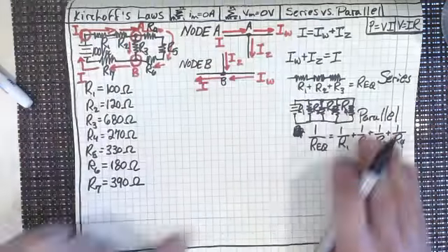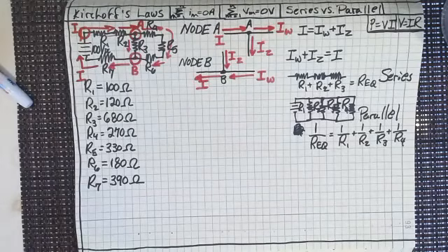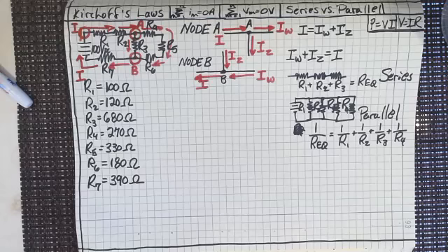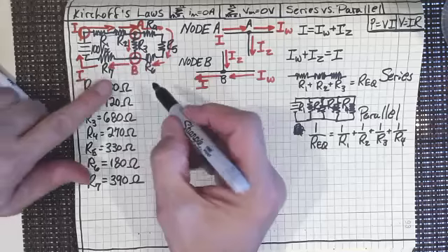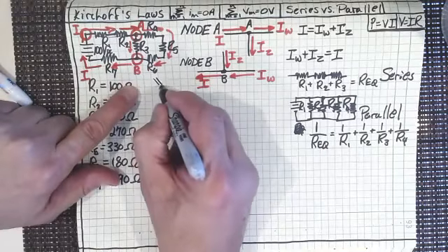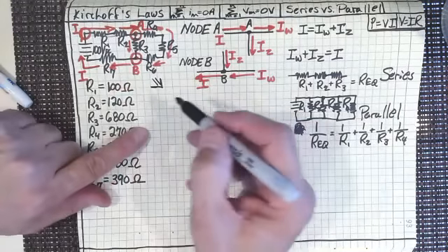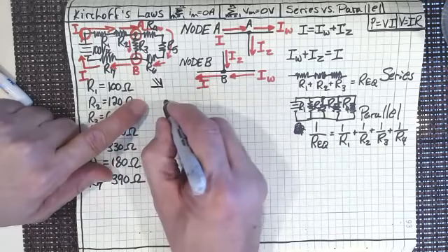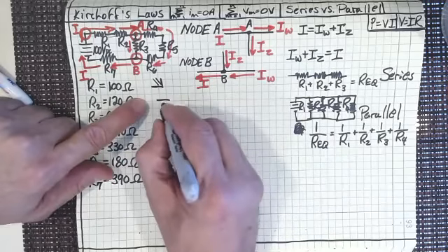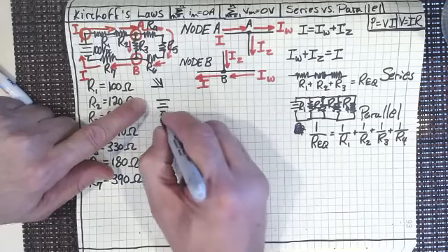And so now what we want to do is break down the circuit into what parts are series, what parts are parallel. We want to add up those parts that are in series, add up the parts that are in parallel, and get it all together so that it comes to one resistor, right? So really what we want to do is take that circuit right there, and what we want to do first is get it to this circuit right here.